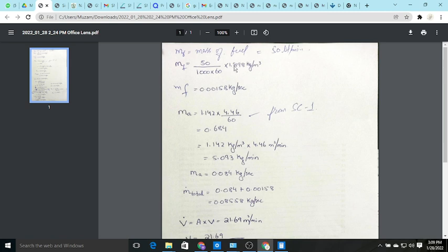I've taken some student parameter, like 33, I think I take this density at 33 temperature. So we get the volume flow rate V dot, multiply by rho, we get the mass flow rate. Okay, so this is wrong. This is not mf. This is the volume flow rate, 50 liter per minute. This is mass flow rate by multiplying the density at that temperature.